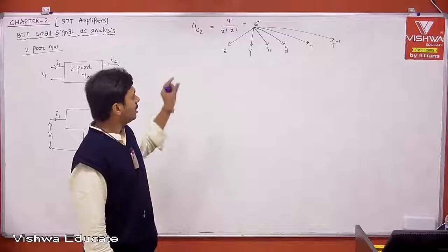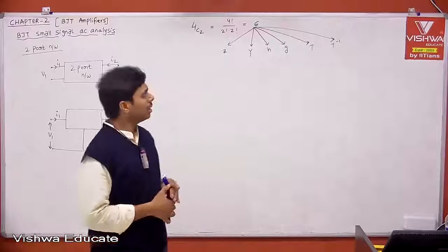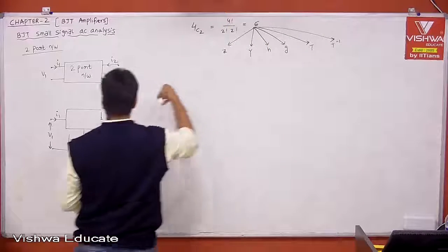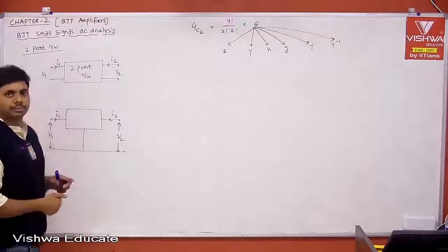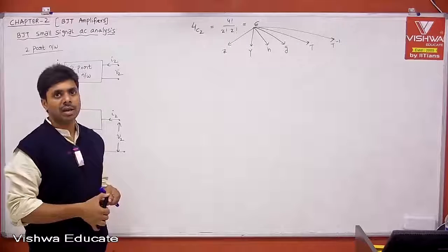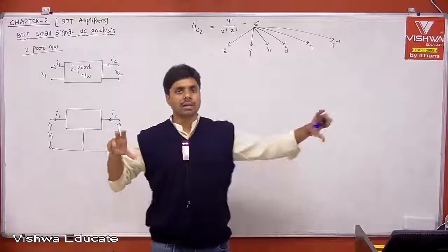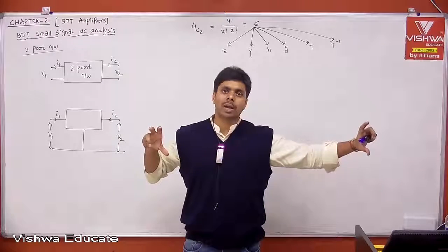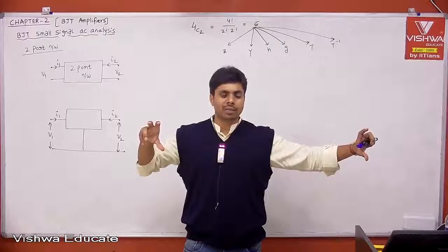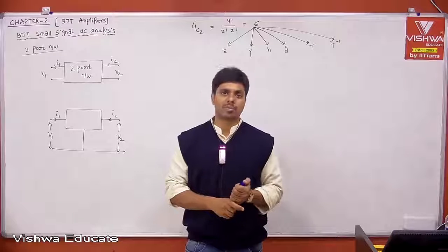Whatever may be, this is what we use. Remember, each combination set will have different applications. You can pick one of the models to define your black box and go ahead, but which one suits best with respect to the application is what people consider. Let us say transmission line theory, where we give input power V1 I1, then output power to the substation or the load V2 I2, and in between we have the channel or transmission line. I want to know output to input, so we can characterize the channel with respect to V1 I1, V2 I2. That is the T parameter model.